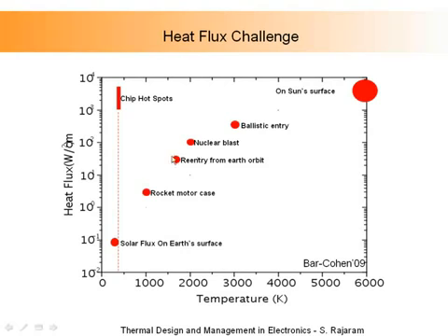And the heat loading on that is roughly about 50 watts per centimeter squared. But those rockets are designed, the surfaces are designed for reaching a temperature of 1600 degrees C. Now, ultimately, if you look at the surface of the sun, the surface temperature of the sun is about 6000 degrees K, and on the sun's surface, the heat fluxes are typically in the range of about, say, 10,000 watts per centimeter squared, somewhere in the 5 to 10,000.